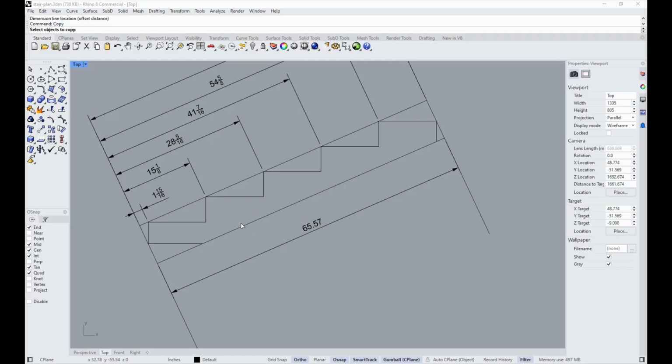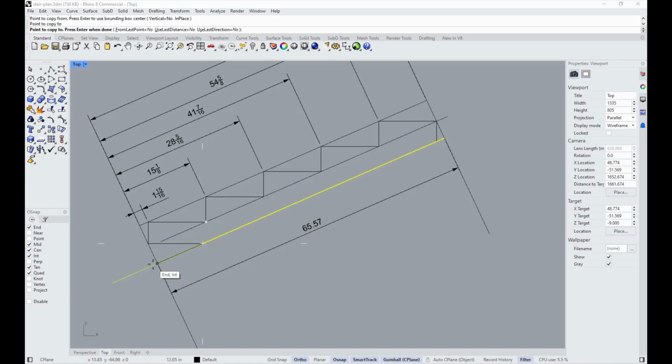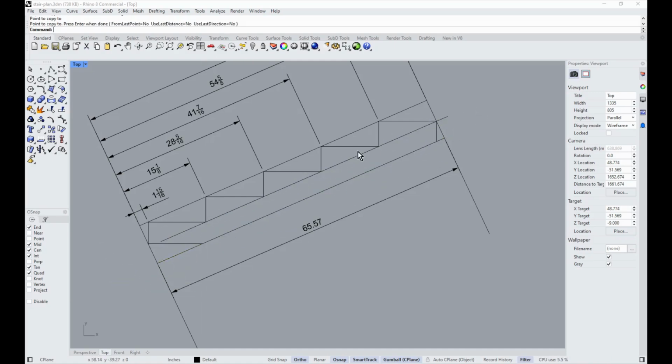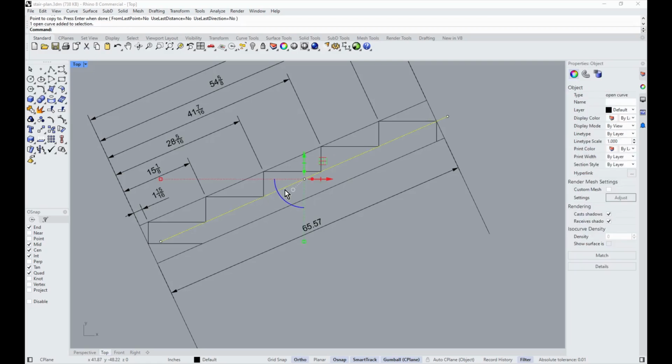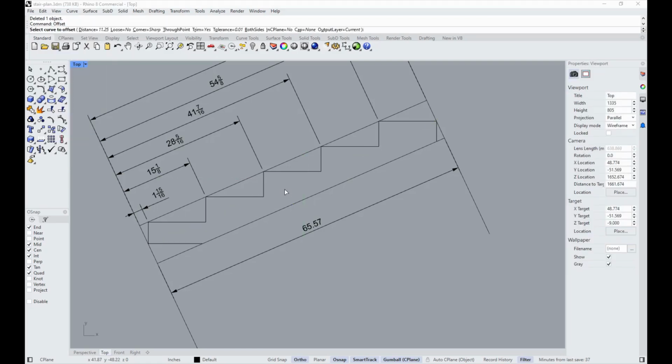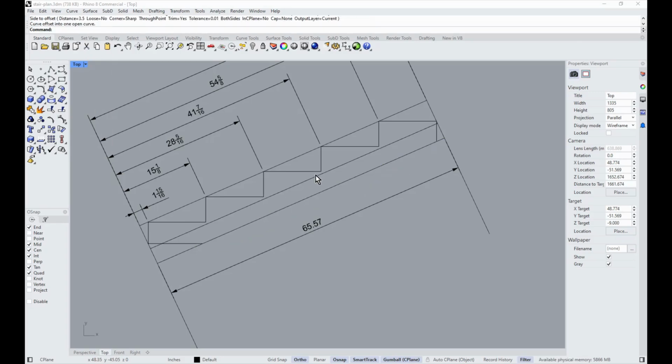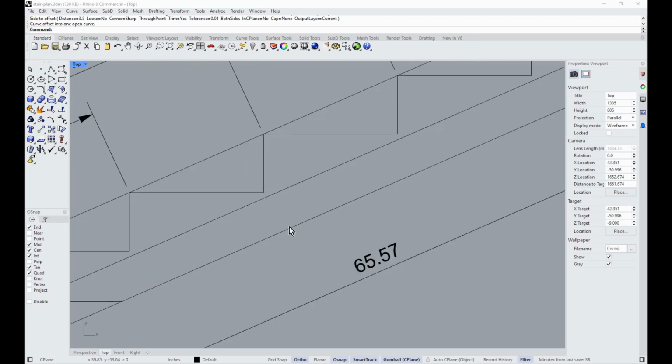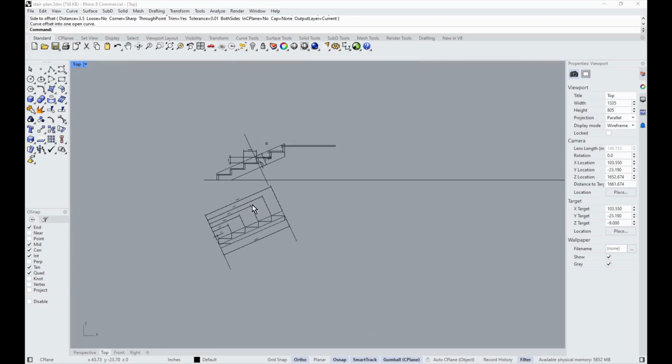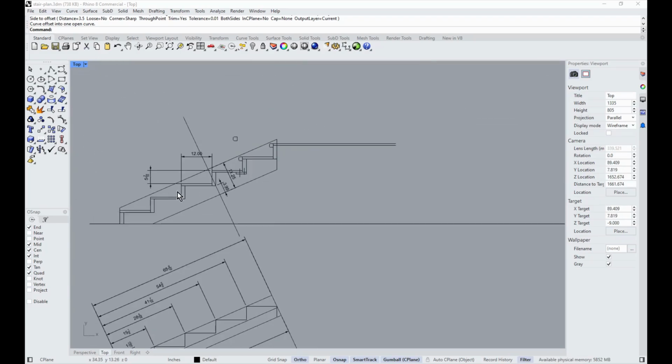You would basically just grab a 2x4 and double it up right there along the side as it goes up. Or we'll do it more accurately. Let's see, offset 3.5. There we go. A little bit of a gap there, but once you make your stringer, you just double up with a bunch of glue and nails, and this will help make that a tougher thing. That's what I did on the staircase that I most recently built. So that shows you how everything works there.